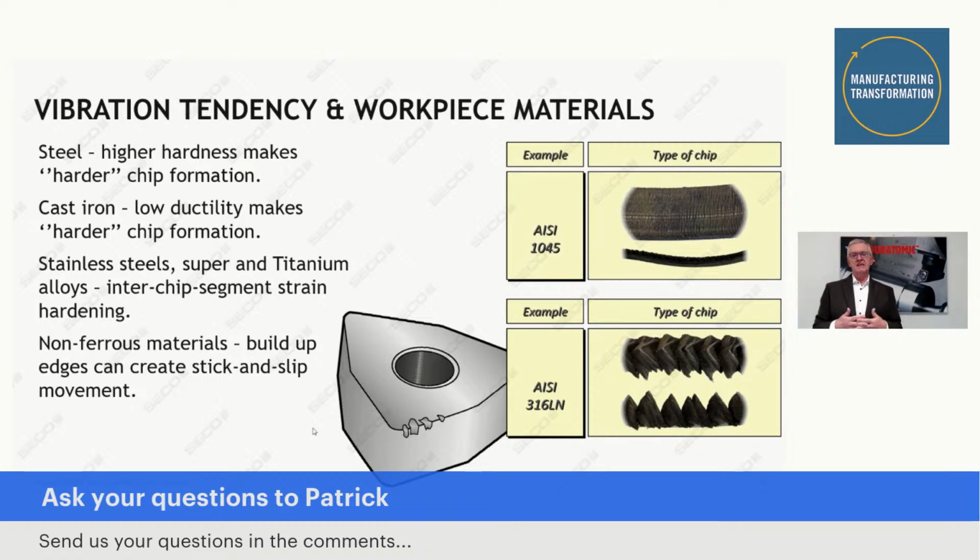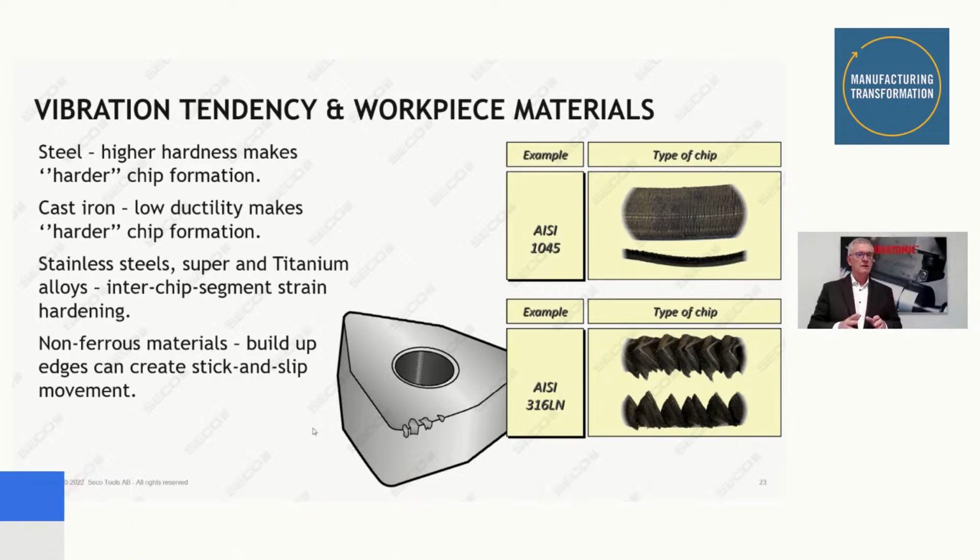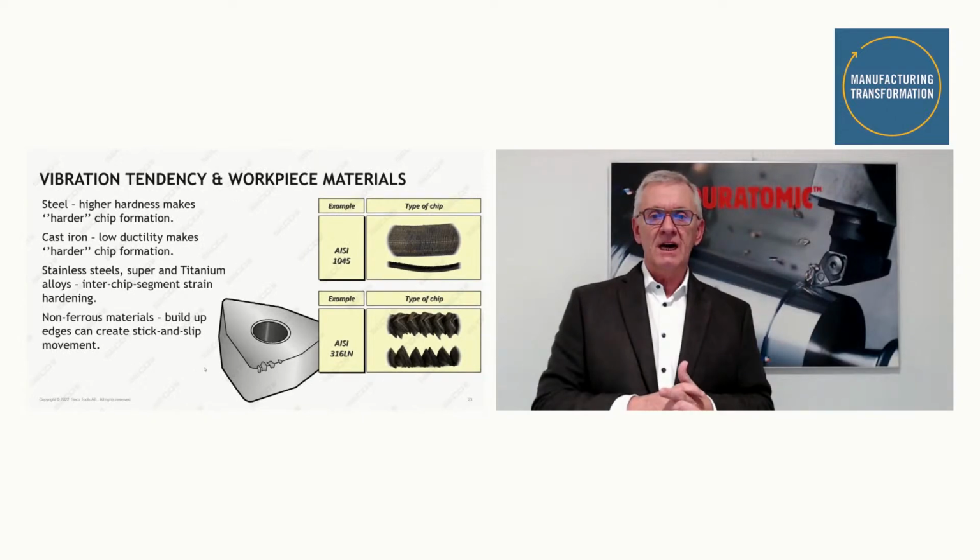If you see very heavily segmented chips, or if you see, without obvious reasons, that quite a lot of cutting edges show chipping to a rather big extent, those are 2 practical indicators that there is a risk that micro vibrations, in a very sneaky way, unheard, are killing your cutting edges, are killing the efficiency, the effectiveness, the reliability of your machining process. So watch out for those.